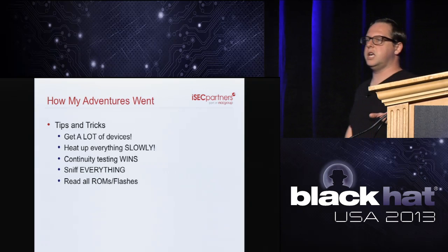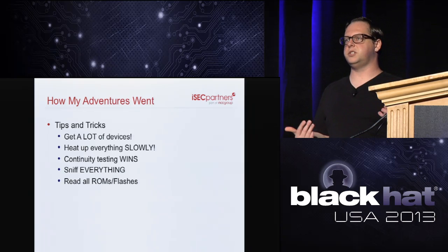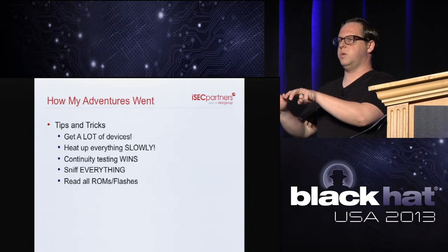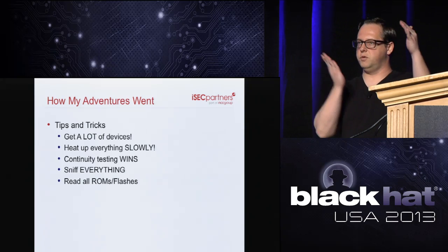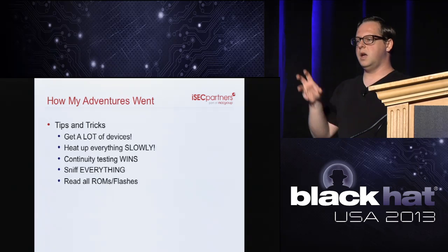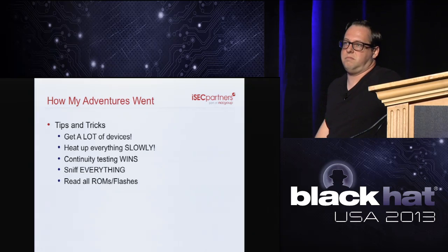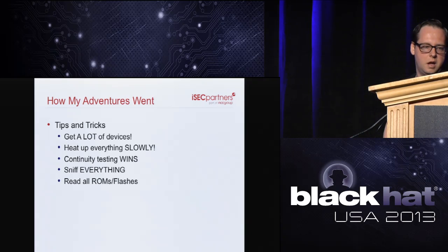I only had an 8-channel logic analyzer, so I picked 2 reference channels, which were the UART ones because they started first, and I said UART lines, 6 wires, UART lines, 6 wires, UART lines, 6 wires, and then I grouped them all together so I had a reference. And read all the ROMs and flashes that you have, and pull out interesting information on that.